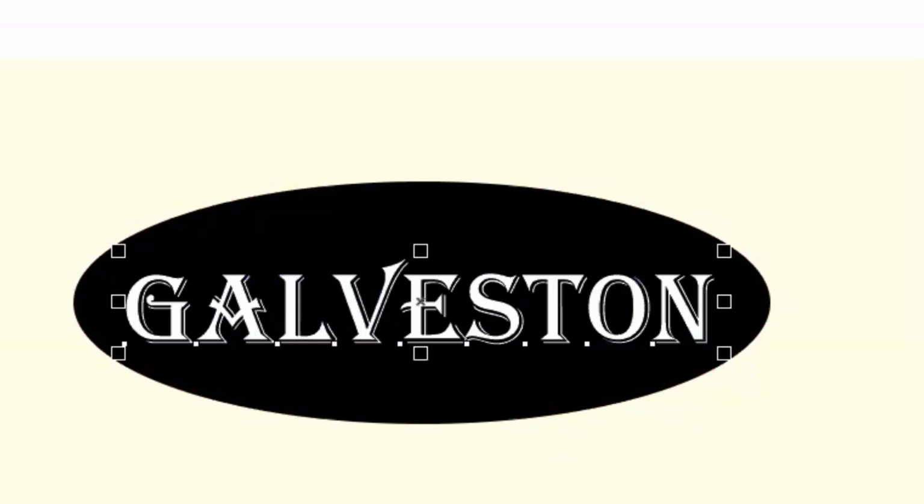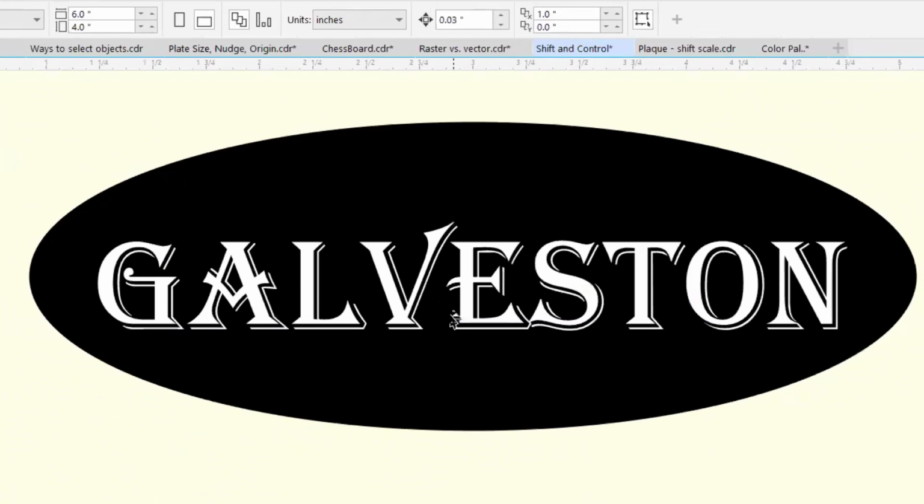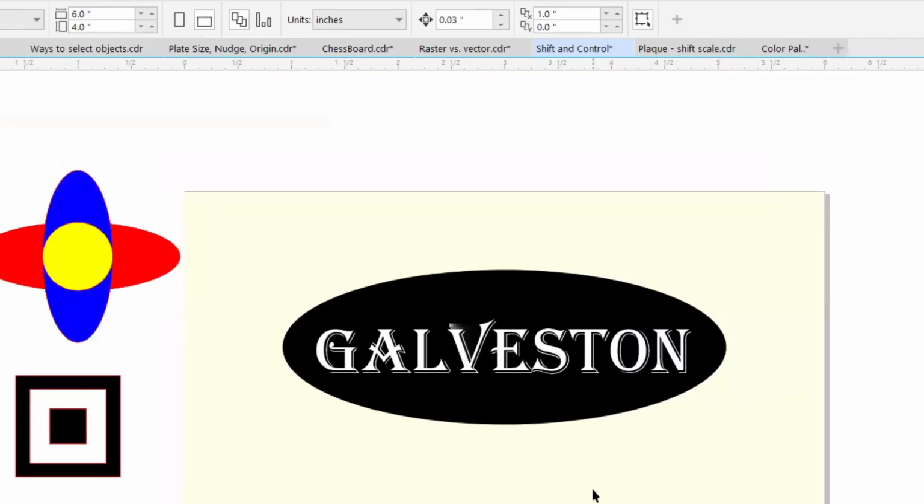I changed Galveston to blue just so it wouldn't disappear on us. I'm going to change that to RGB white. So what we have here is actually going to be raised text. This text is going to be left alone and all the background is going to engrave. So a real simple way to create a raised text effect is to put some sort of shape in the background, fill it with black, and then change your text to white.